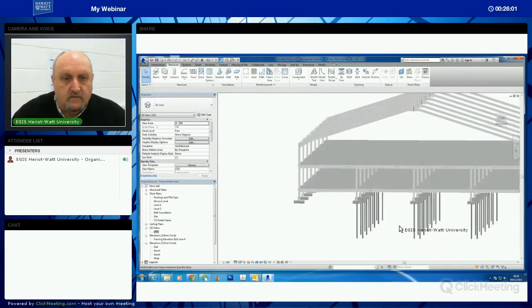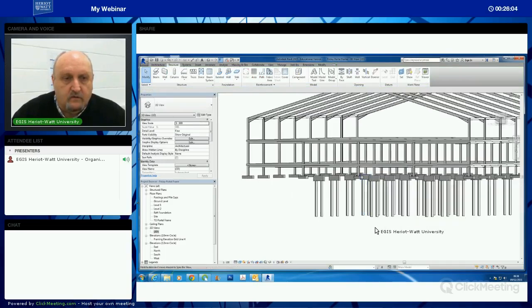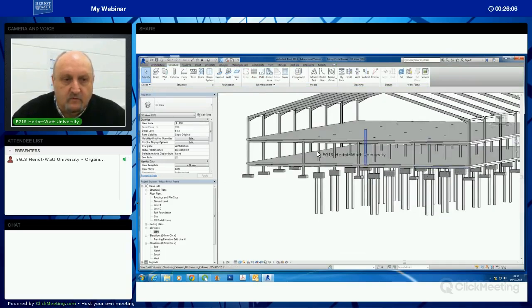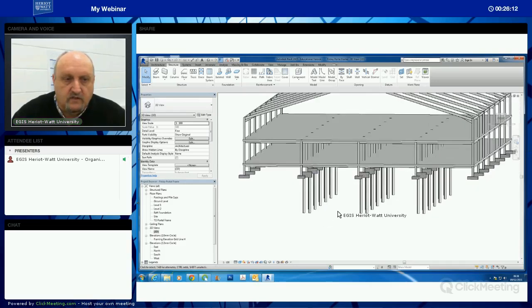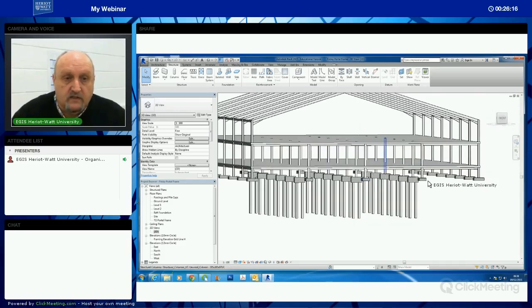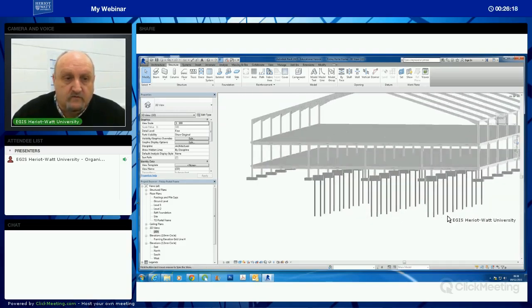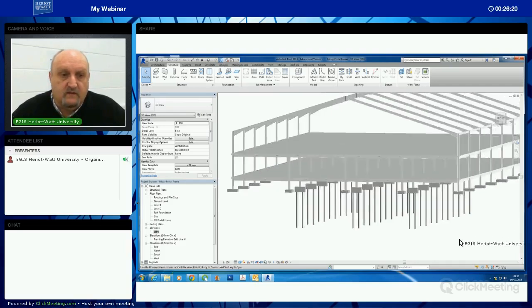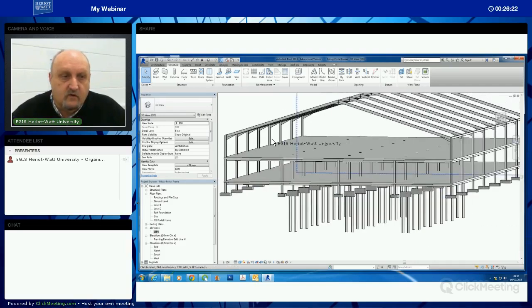And that shows you the comparison between the floor, which isn't really benefiting from the portal frame on this floor here. There's lots of structural columns going in here. They will put structural walls in here. Sorry, put partition walls in here. We don't need anything else structural in this building. Portal frame will do that for us. But the advantage of having the portal frame is the open space on level 1.